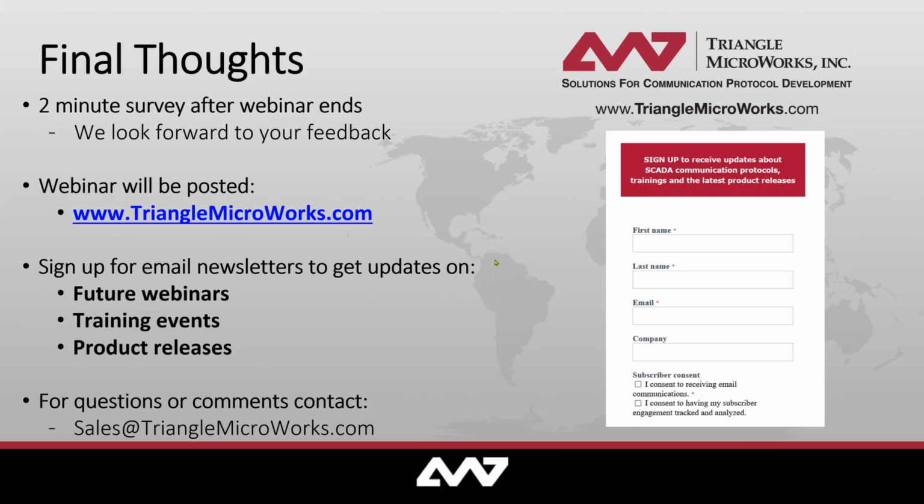Thanks, Beth, for the question. Yes, there is. Like we have the IEEE standard for the mapping of 61850 on DNP3, within the IEC 61850 series there is the technical specification IEC 61850-80-1, which addresses the mapping between 61850 and the IEC 60870-5-101 and 104 protocols in a similar way.